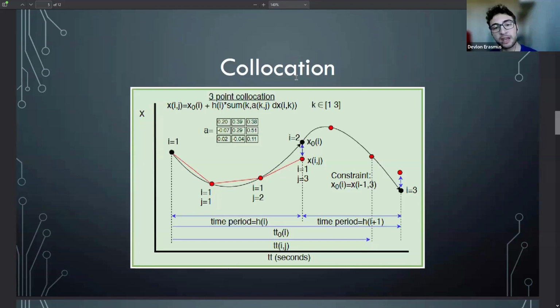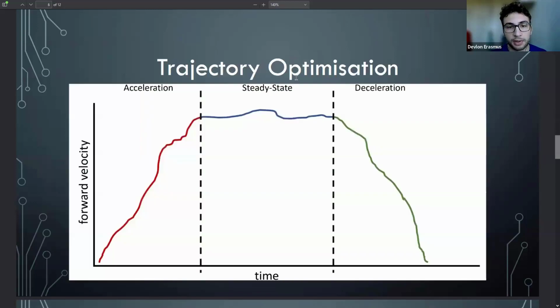Some extra techniques are used to allow the generated path to be smoother, since it's a bunch of nodes as shown on the screen. One is to use collocation. This basically breaks up the path into 3 smaller points, as increasing the node points of the robot makes it longer to solve. This technique has been shown successful in studies to keep nodes low while increasing the accuracy of robots. Some extra constraints are then applied in the actual optimization problem to allow the points to match up to where they should be on the actual path of the robot.